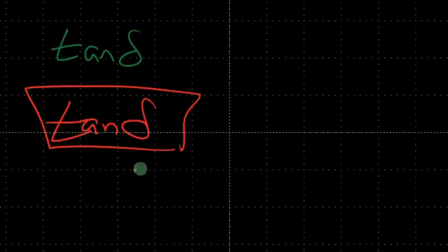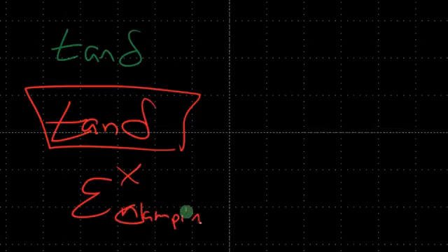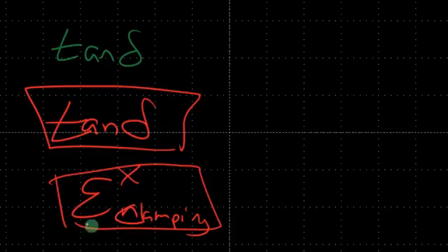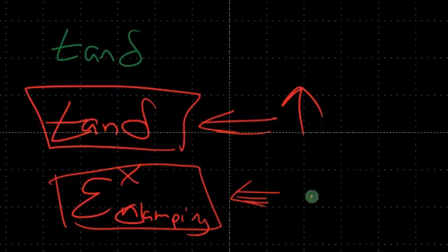If you look at the tangent delta and the effective new permittivity from the clamping, you can get a really good idea about how you bonded it. So this determines the loss properties, this determines the real properties. This number will go up after clamping, this number will go down after clamping.